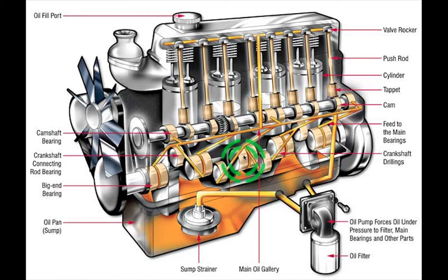So your crankshaft is actually not rotating directly on the bearings. It's not metal to metal. There is no metal to metal friction. There is oil 24/7 between them, like a film, because if metal touches metal, it's going to heat up, there's friction, it's going to bend, it's going to get scarred, right? So there's always oil between them. That's why you can't run it without oil.